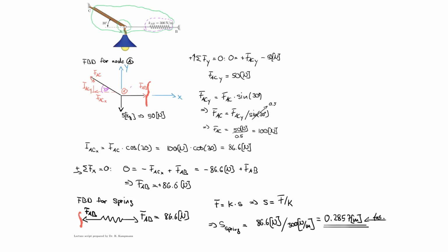And once I knew the force in that spring, I just applied it to the spring, and then I calculated the stretch in the system. And it's literally as simple as that. So really what you need to learn is how to find equilibrium at nodes. So let's make that a little bit more complicated and take a look at more advanced examples.